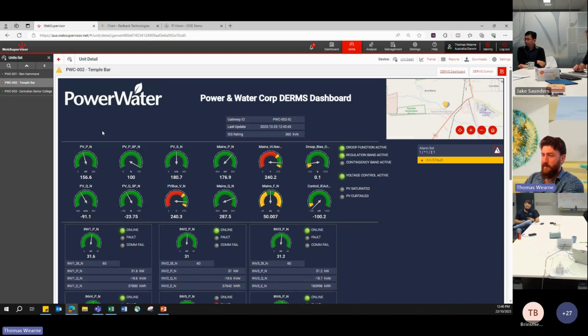It then gives you this sort of menu that a customer would connect, and we could set the type of voltage control we want. If you wanted the droop control, et cetera. It's all basically adjustable, and because it is lines of code, it doesn't change the per unit cost once you've developed a particular capability.